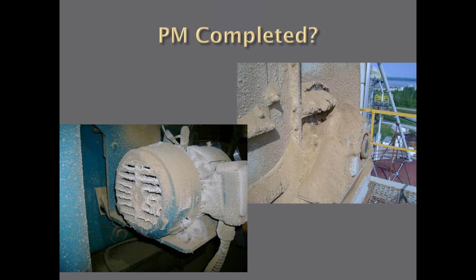So again, once the operators and maintenance knew what the effect of that was, motor temperature. Now, what does motor temperature mean to an electric motor? Well, for every 18-degree Fahrenheit rise, or about 10 degrees C, you cut the insulation life of the electric motor in half. So here, by lowering the front bearing temp, lowering that motor temp 35 degrees, we actually extended the insulation life by almost 4 times.